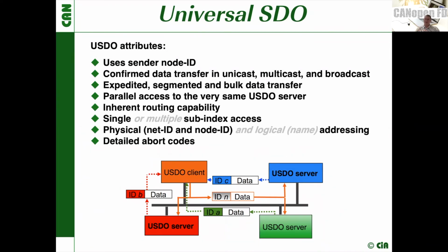At the moment in classic CANopen, we always had to wait till an SDO access was finalized to initiate the next one. Now we can do everything in parallel. Furthermore, we have updated the abort codes to provide a lot more detailed diagnostic information. And finally, we have many doors open to future extensions, for example, navigating through CANopen FD via browse names and so on.